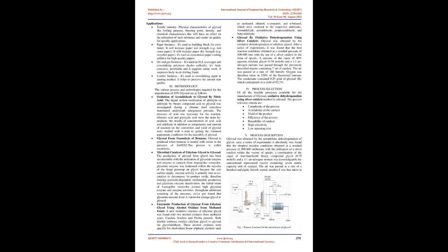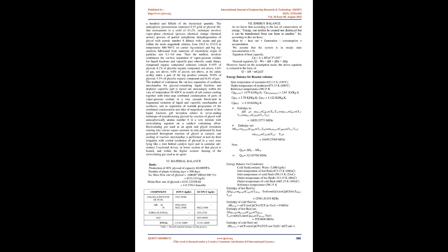Methodology. The various processes and technologies required for the manufacture of 40% Glyoxal are as follows. Oxidation of acetaldehyde to Glyoxal by nitric acid, the liquid phase. Oxidation of acetaldehyde or aldehyde by nitric acid to Glyoxal was investigated in a stainless steel autoclave maintained under autogenous pressure. The presence of acid was necessary for the reaction.